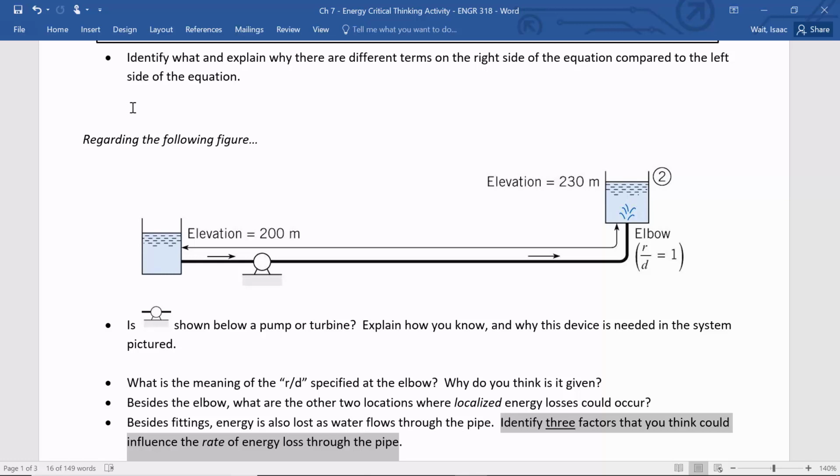And look, diameter is down in the denominator. That's only going to amplify the effect, because if you have a small diameter, now you've got a small number in the denominator and a bigger velocity. So small pipes lose energy much more quickly than large pipes. That's why, if you're designing a water network in a city, you have to ask yourself how big the pipes should be. It's all about managing pressure. You'll do this in the project that we have next semester in hydraulic engineering. You're going to be asking yourself, do they have enough pressure at this part of the city?